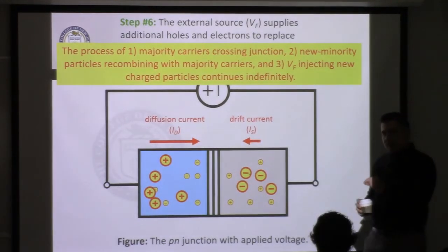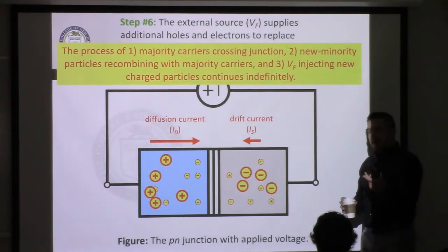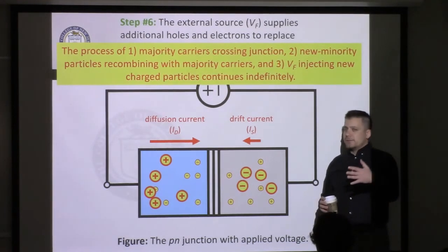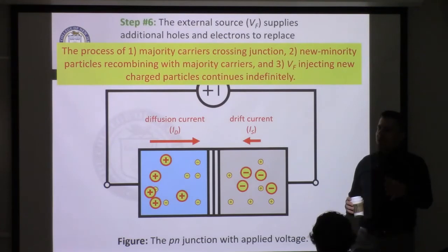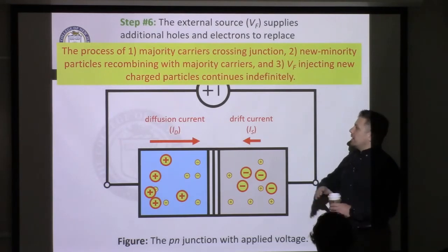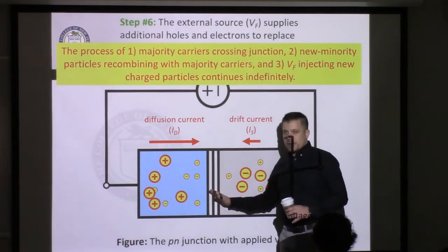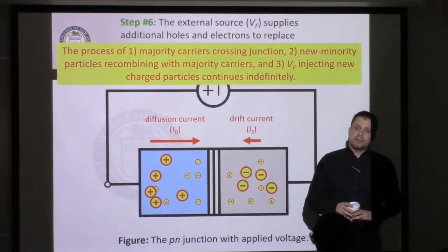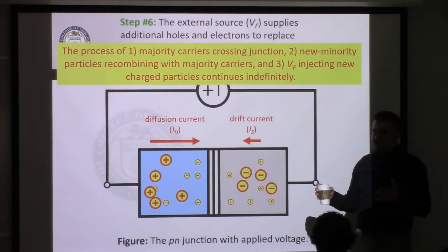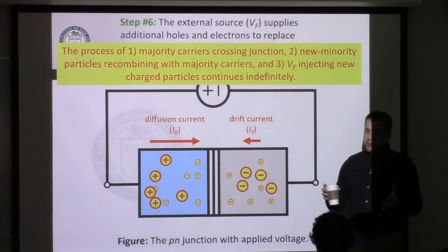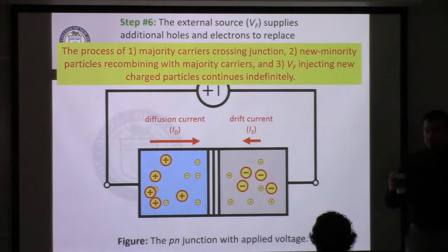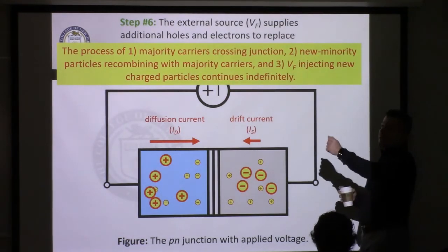So it's a little bit unexpected that a voltage source is sort of controlling the rate of diffusion, even though diffusion current is not dependent on electric field. It's an indirect relationship, because the EMF is affecting the depletion region, and the depletion region is what is affecting the diffusion. So funny enough, it's diffusion which is the governing current flow that we have within the pn-junction, and not drift current, which seems counterintuitive given the fact that it's affected by a voltage source.